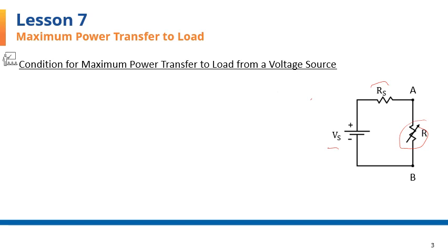The current through the resistor is calculated as Vs over sum of Rs and R, shown here. The power delivered to R is found as I squared R. Substituting for I from top line, P sub R, the power consumed in the resistor R, is going to be equal to this expression here, V sub S over R plus Rs, quantity squared times R.